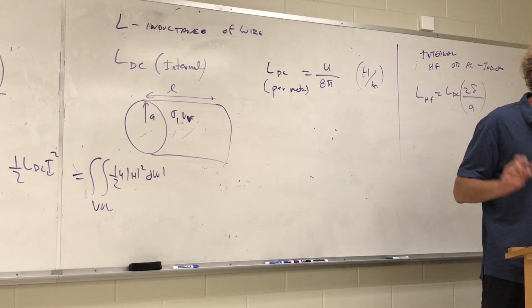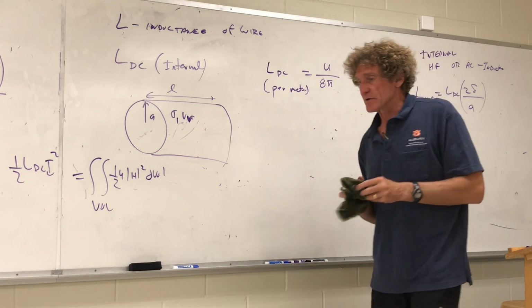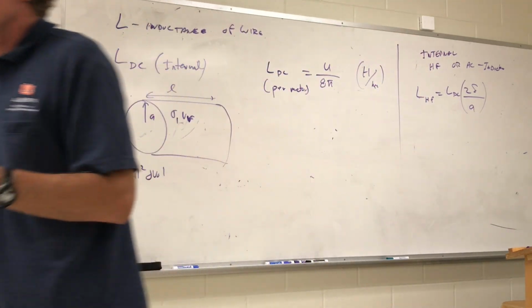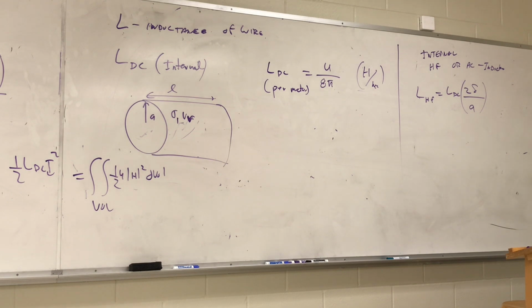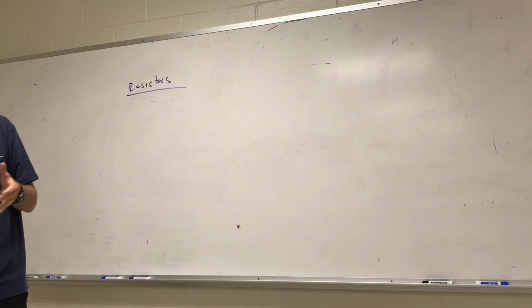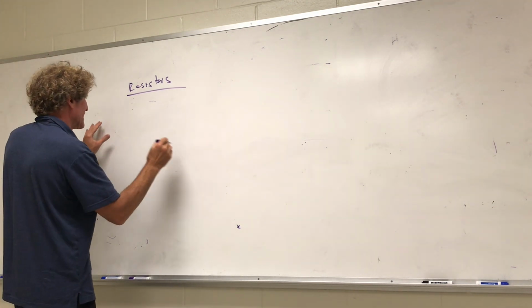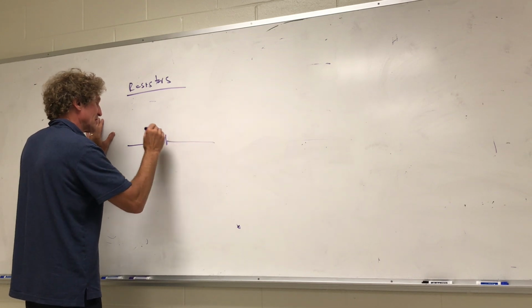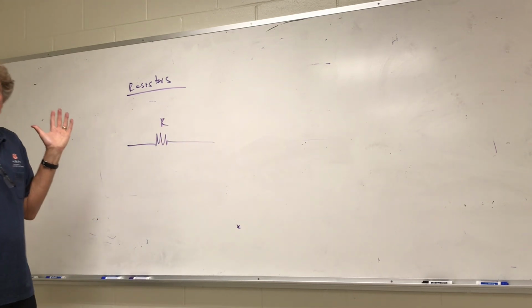We're going to talk about what a real resistor looks like, and a real inductor, and a real capacitor look like at higher frequencies. And this is real important because most of the equipment you work on, especially with amplifiers and stuff, are designed for what I call low frequency operation. But oftentimes they get pushed into the high frequency range by necessity, especially with these amplifiers that are like class A, B, and stuff like this, where they're at higher frequency and they're pulsed. A resistor at low frequency looks like the element you want it to look like. So a resistor looks like a resistor at low frequencies. At low frequencies, they all should look like that.